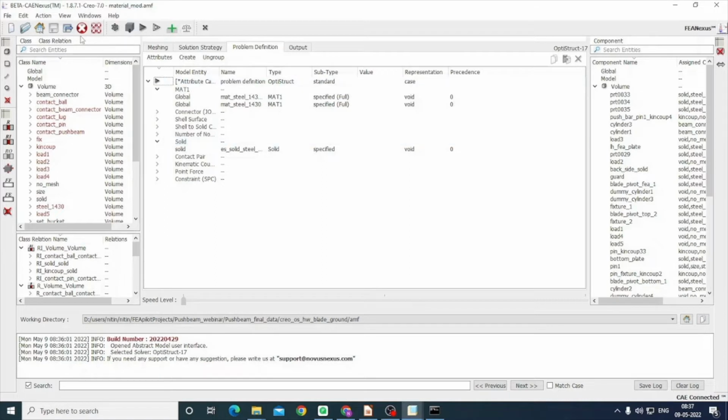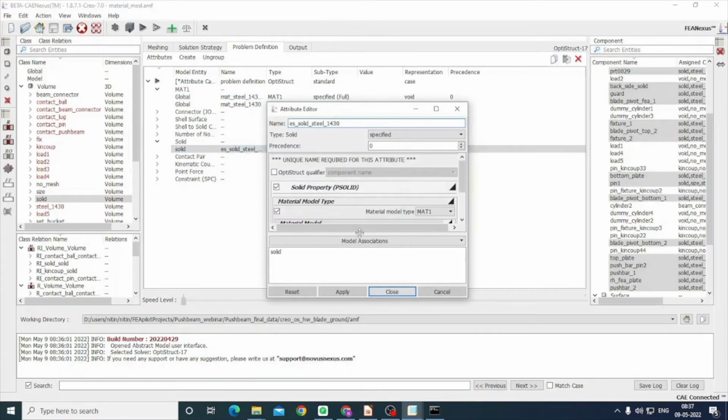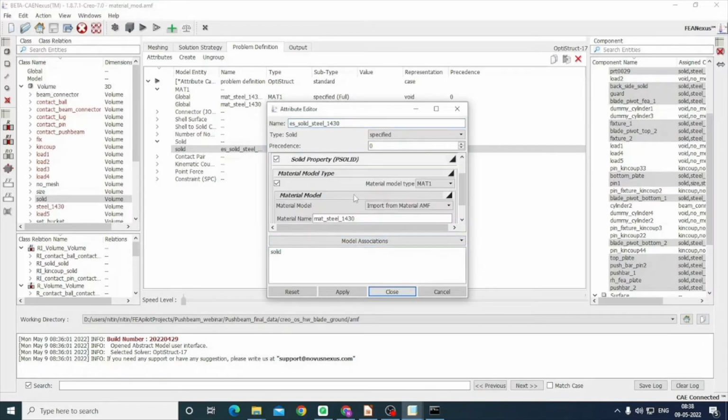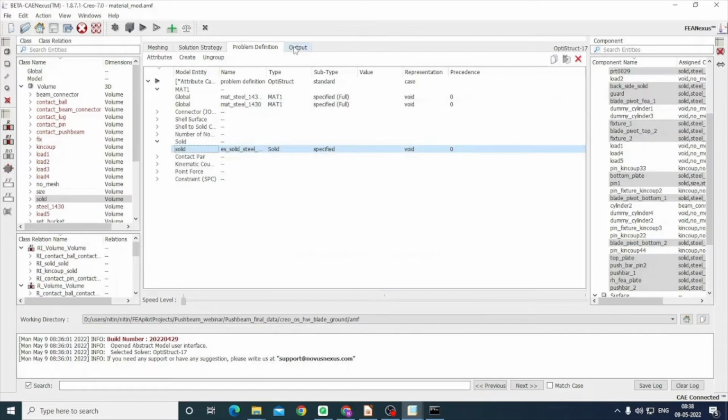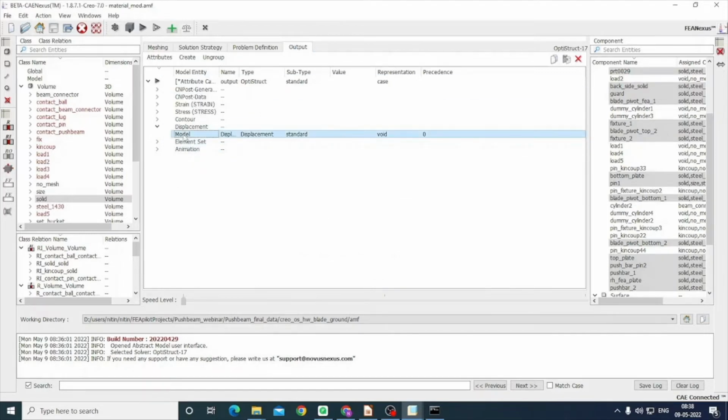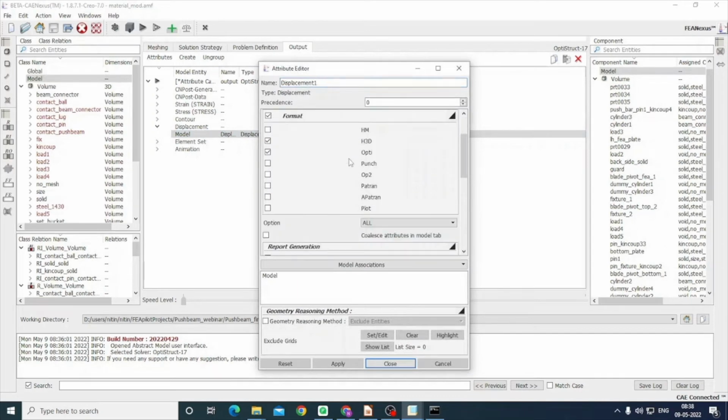Over here you see that there are classes, no physical geometry, just abstract placeholders, titles that will represent actual geometry. For example, you can see that we have designated here under this solid class specific material properties that are specific to the OptiStruct solver. Anyone familiar with that is already putting these properties in every time they do a simulation. Here you can put it once on a placeholder entity called a class, where these physics properties and attributes will be held.